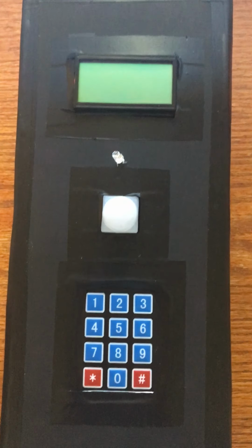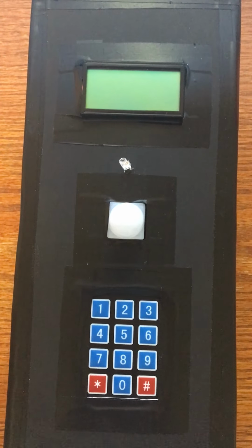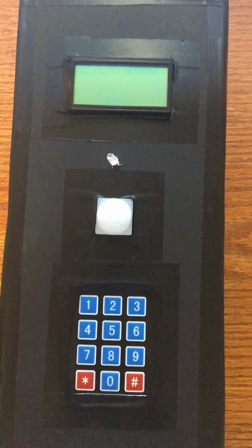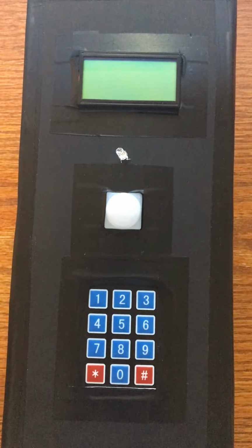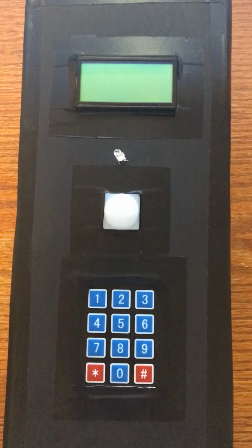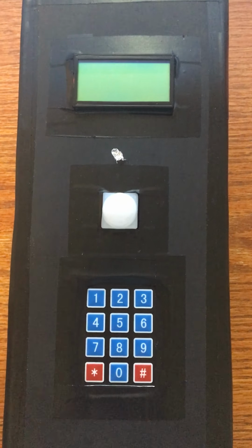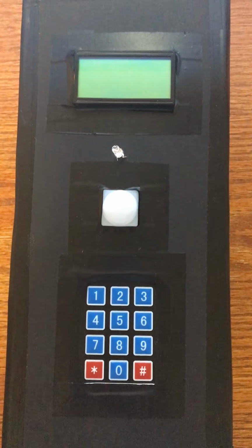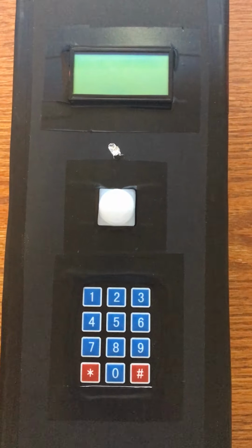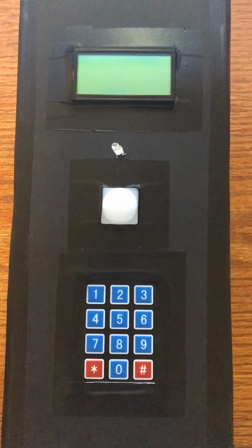During the intruder detected stage, the SPI is initialized and the DAC is configured to output a DC voltage of 3 volts, turning on the LED. Next, the software architecture initializes the LCD, clears the display, and sets the cursor at the beginning of the first line. The software architecture then displays the message intruder detected. Then, the software architecture reads the keypad input value.